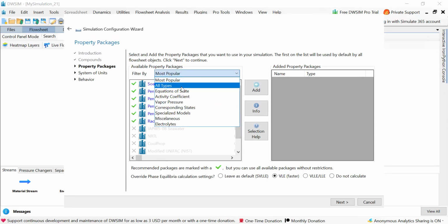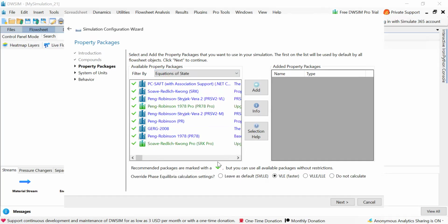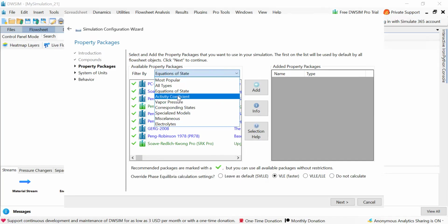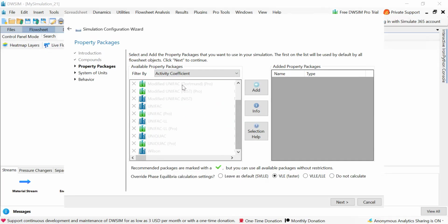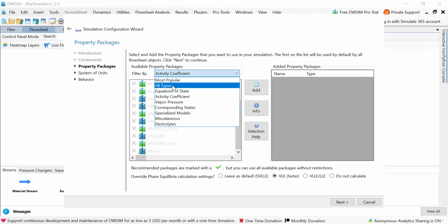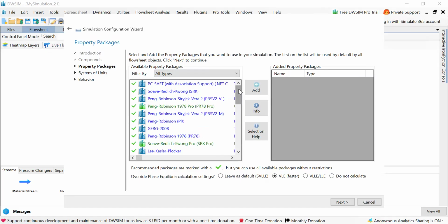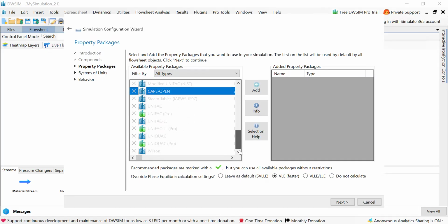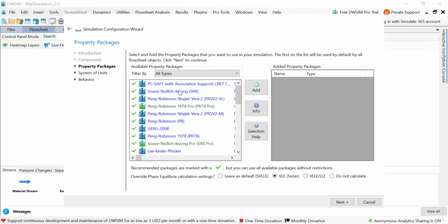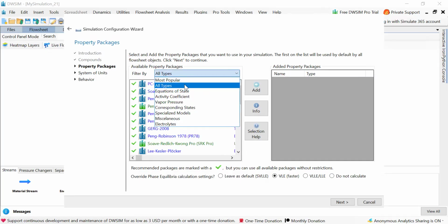But for the sake of utilizing a thermodynamic property package, I would like to take up any other package. Every time whenever we choose one particular system, it automatically tells us which thermodynamic package can be chosen. See, it is not showing NRTL, it is showing Raoult's law, Soave-Redlich-Kwong, right?